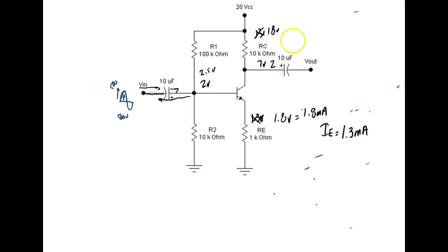So if this is 18 volts, this right here would drop down to 2. So while we were sitting here, we were originally setting up here at 7 volts. What we did now is we just dropped down to 2 volts. So 500 millivolts in, 2 volts out. See that? 500 millivolts in, 2 volt change out. Now, of course, on the input, we're going positive. The output's going negative. It's not going to go negative, but it's moving negative, right? Because 0 is down here.